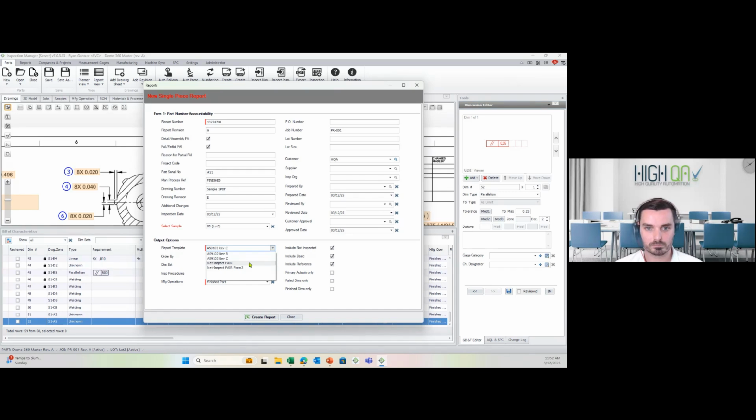We have another question about whether the software can read CAD models, IGES, or STEP files instead of a drawing. Yeah, we do support 3D capabilities. As long as there's PMI embedded in there and GD&T for us to extract, we're going to be able to automatically extract all the GD&T. At that point, we extract it, convert it to a 2D, and go through the same process that you saw here. The main thing is making sure it's a native file and has PMI embedded in there, and we can certainly work with it very nicely.